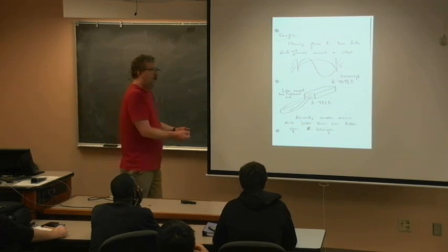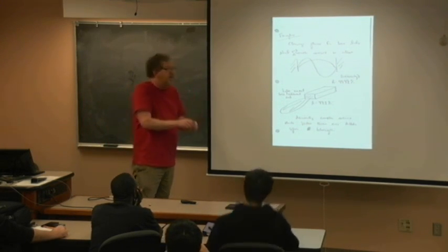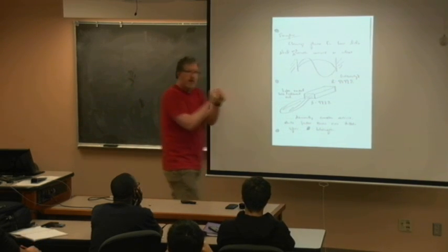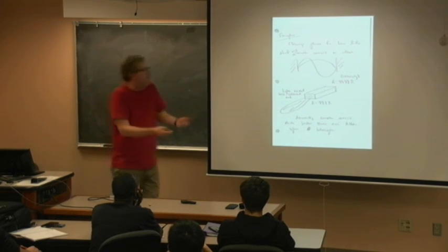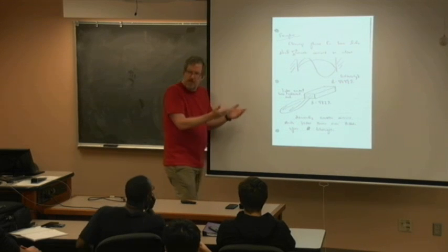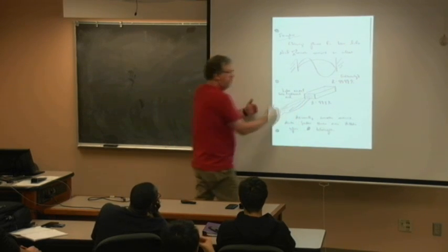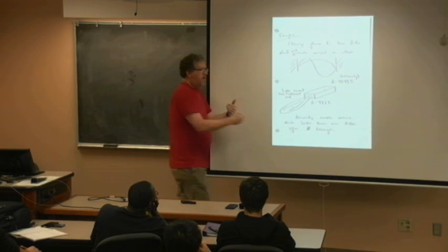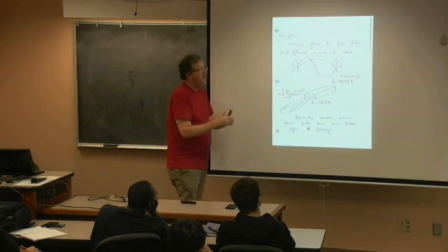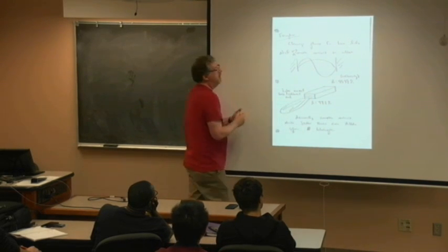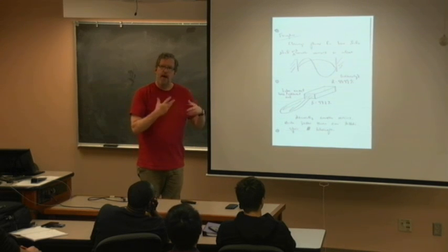So because of the crystallography, you can be like a diamond De Beers. I can go in and cleave along the crystallographic facets, just like I'm cleaving a diamond. And I've done this. It's actually fairly simple. It's tedious, but it's simple to do. And if you get two perfectly cleaved facets, then they end up being quite reflective, and you end up with this Fabry-Perot cavity, which it seemed like people had not really seen in prior classes. Fabry-Perot in physics.